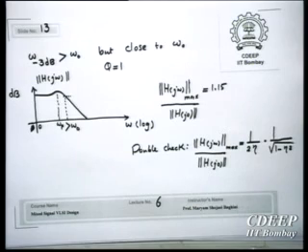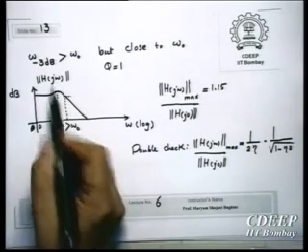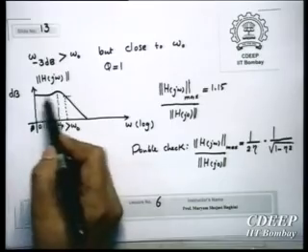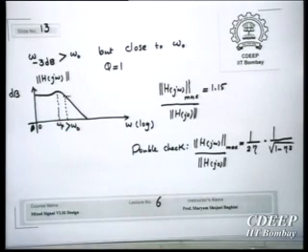So there is a peaking. Sometimes this peaking is too high, which means the filter actually has a very high Q, so it is used as a band pass filter. Because this can create a narrow band pass filter, and it can peak to a very high value, and this will be actually 0 dB gain or some small gain, which is not important. Okay, so this was an example of a multiple feedback filter, which is, of course, as your friend said, economical because the number of op-amps used is less.